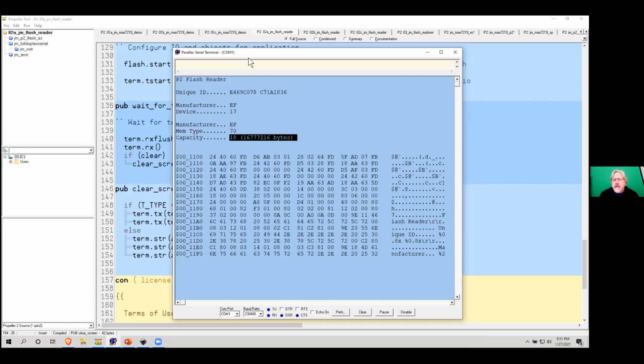User data, though, could be changing a lot, especially in a data collecting type situation. So that's where you're more concerned about the wear level. We just don't do anything with the memory above 512K because that's as big as your app can ever be. So the memory beyond that, we never touch. You would need a file system in the form of an object to access it.